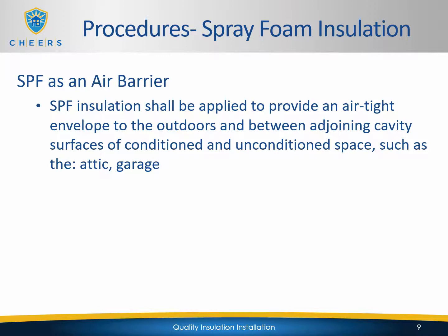Also, SPF insulation shall be applied to provide an airtight envelope to the outdoors and between adjoining cavity surfaces of conditioned and unconditioned space, such as the attic, garage, and crawl space.